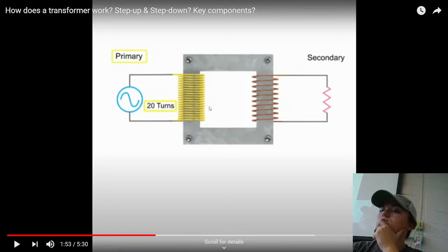We call them step up and step down based off of just voltage, but they're doing the opposite thing to the current. So if they step down by half, they step the current up by double. So when you use a transformer, your current's going to go up. Well, in a step down it would, but in a step up, like if we had a transformer that we wanted to take 1,000 volts, your current would have to come down, because the power that you're putting in has to come from somewhere. We're not going to create nor destroy power, and power is current and voltage. So if we step one up, we're going to have to step one down by the same factor. Okay, I think I agree.